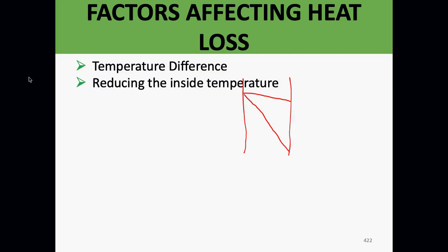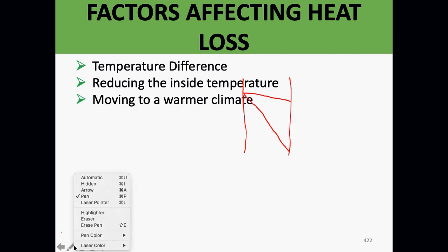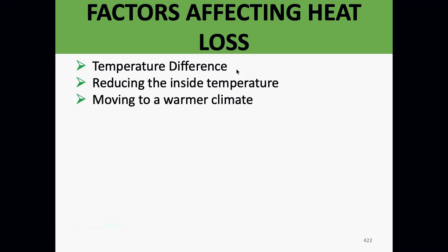We use an average. If I reduce the inside temperature on a cold winter day, I have less of a temperature difference. Yes, I'm going to make occupants very uncomfortable, but I have less of a temperature difference. So reducing the temperature on a cold winter day makes a difference. Moving to a warmer climate, of course, reduces heat load. It's not what everyone wants to hear, but it's there.